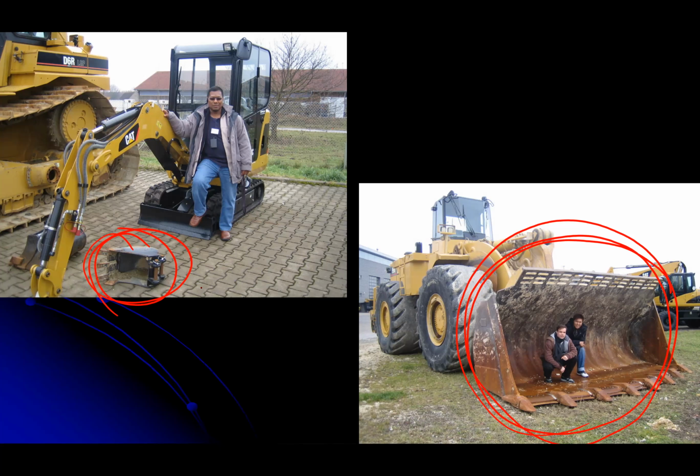Because when you bring a big bucket, basically you need to backfill again. Okay, you need to backfill, and it will cost you in terms of time and energy, etc. So you must choose the right machinery. And all of the construction machinery is usually tied up with what we call cost. The bigger the capacity of the machinery, the more cost that you need to pay.